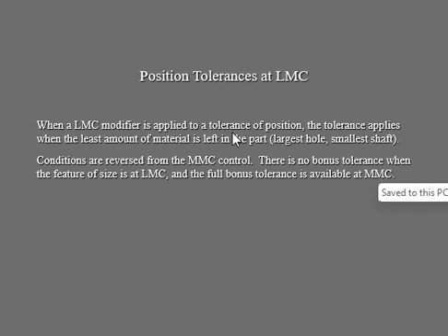Because you still have the position tolerance for that hole, because the hole is a feature on that part, and we're dealing with the position tolerance of that hole, not the hole itself. That's why you have the smallest shaft, because we are accounting for the zone of that tolerance around that hole. Okay, don't forget that. It's very, very powerful. So of course, for engineering drawing and drafting, as you advance, it gets harder and harder because of little things like that. You have to remember all these things in your head all the time.